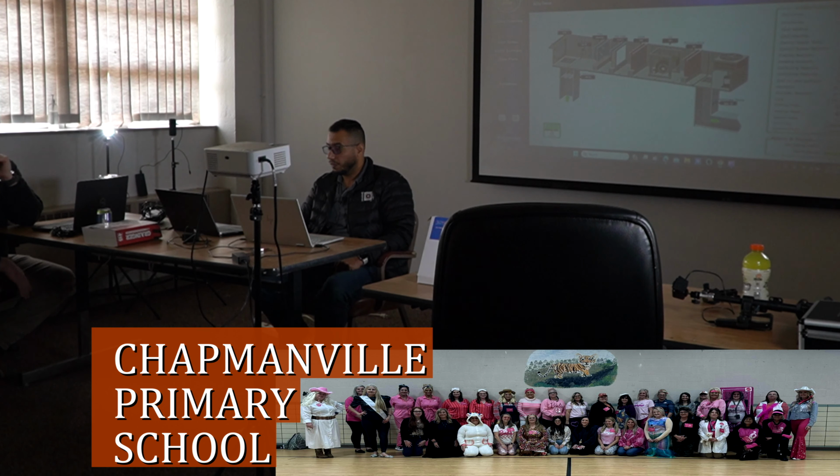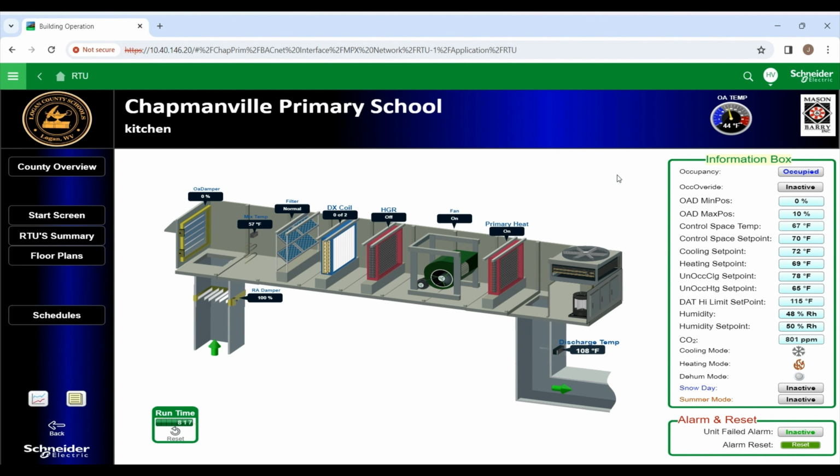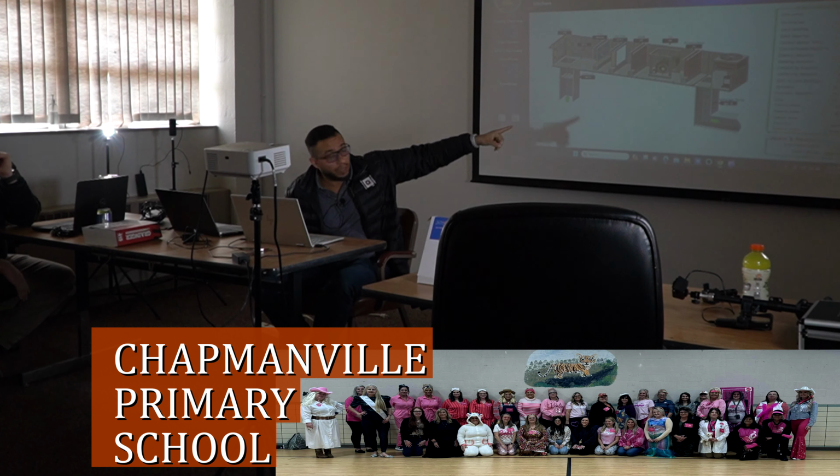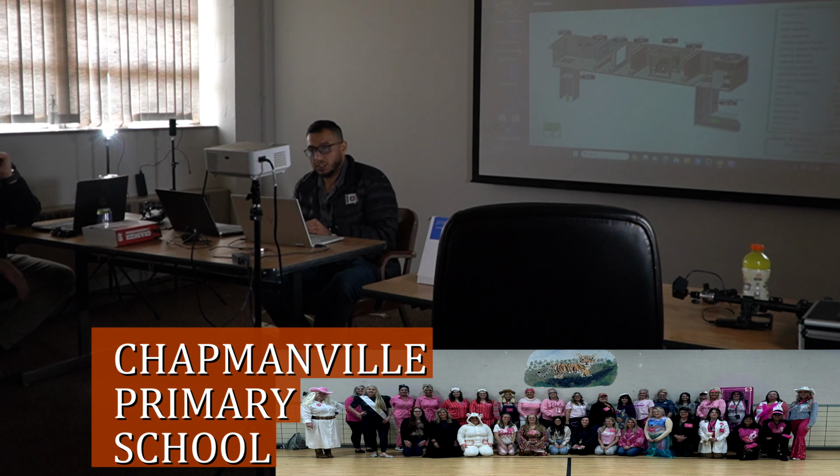Let's do it with the outside air damper. Yeah, if that's all I want to touch. Okay, the outside air. So the outside damper, as I said, I don't recommend messing with it that much. Look at this minimum position here that you see right now. Whatever value you see there, keep it in mind or write it down so you don't lose it. And then you can give whatever number you want, and the damper will follow right away.